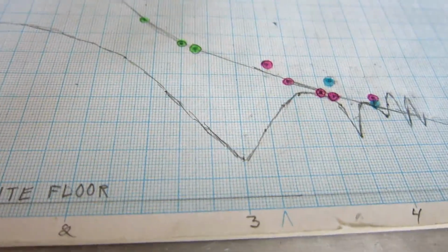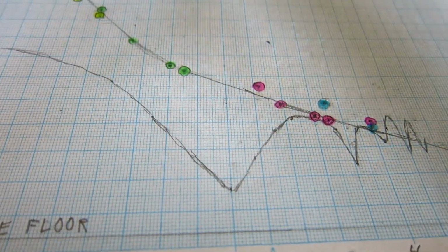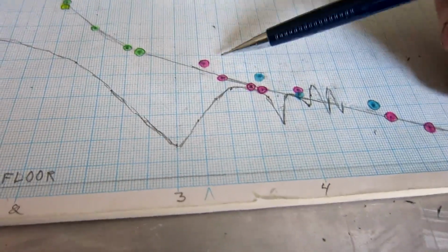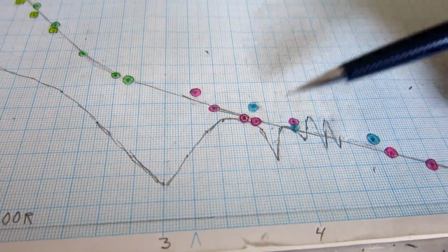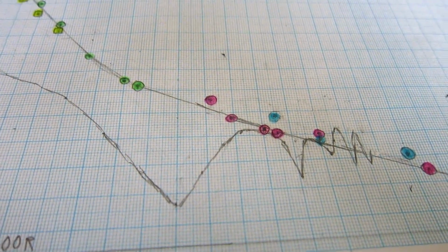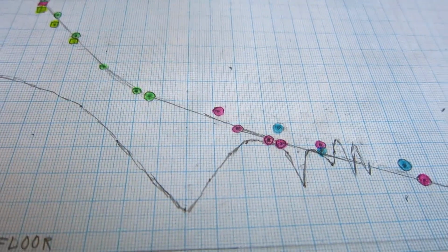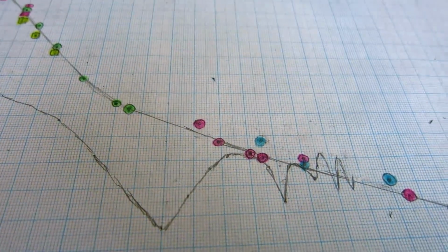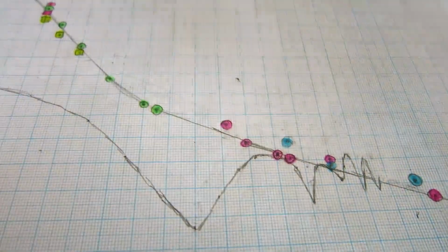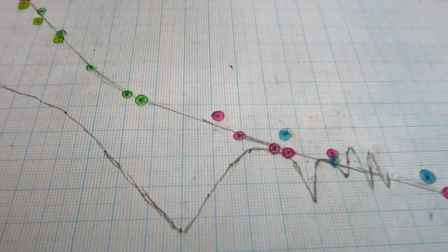Now I have shifted this curve showing the limitation given by the sound card downwards by 5 dB, and I have also put back these points now in red, the first points that I made with the dual precision FFT, and that I rejected because they didn't seem to fit the straight line I had at that time, and they were below this curve where it was placed before.